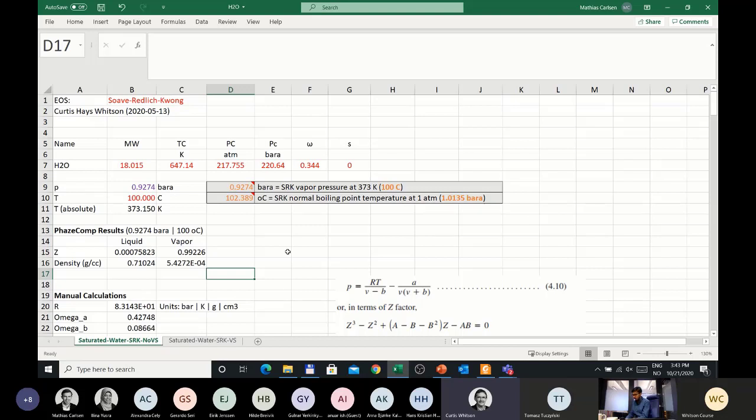And just one comment, Coris. Correct me if I'm wrong. When you're saying that the cubic equation of state model is not predicting the compressibility, it means that the cubic equation of state model is not predicting the variation of density with respect to pressure, right? So you can use the volume shift to match one density point exactly, but you may not get the function of density as a function of pressure.